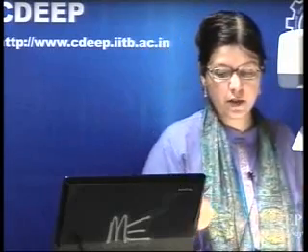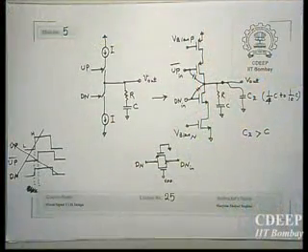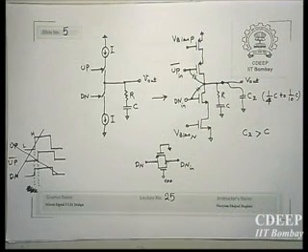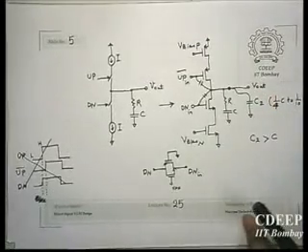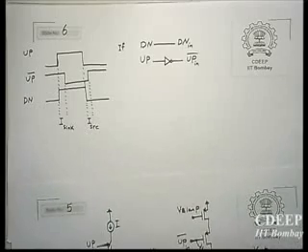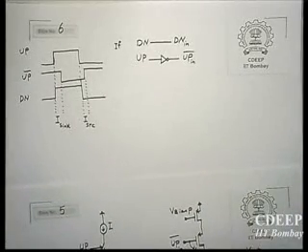Not only that, this mismatch changes with Vout level. If Vout is very high, I source will reduce. If Vout is low, I sink will reduce. So this mismatch between these two currents is one of the main sources of error. That's why a cascode with a high output impedance is definitely the right choice.